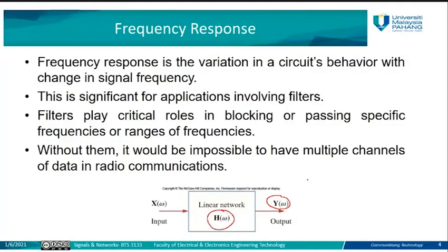As we said before, the transfer function can be written as G(s) or H(s) or any other name. But when we talk about frequency response, our focus will be more on the omega value. Why omega? Because, as we know, s consists of a real part and an imaginary part when we represent it using the s-plane. The real part is the sigma value, and the imaginary part is the j omega.